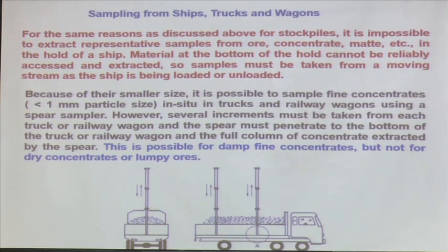So, what I suggest is that ultimately you are using a wagon tippler, it is going to a bunker, from that bunker you have a chute and then you transport it through a conveyor belt. So, why do you not sample it on the conveyor belt, in the moving stream? Then your entire problem is gone, and your sampling is much more accurate. From a wagon it is very difficult to do sampling, it is basically not ideal, but it is being practiced.